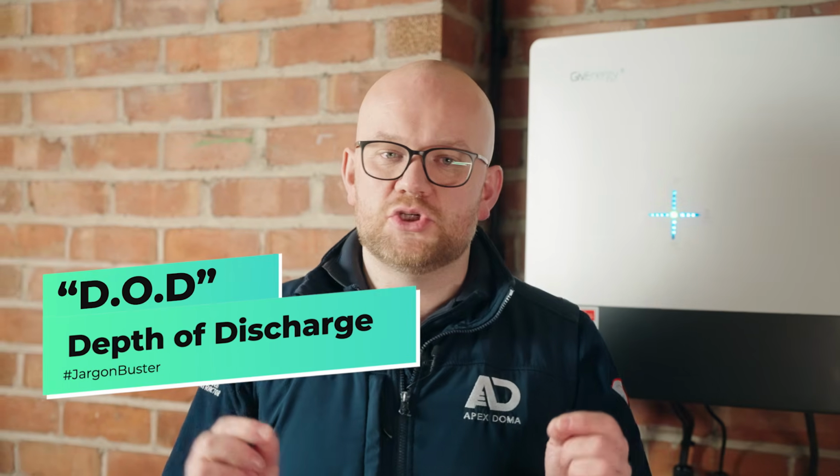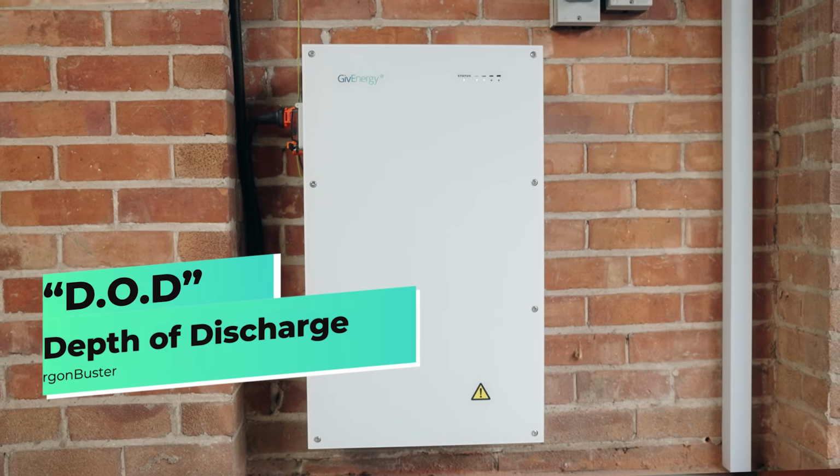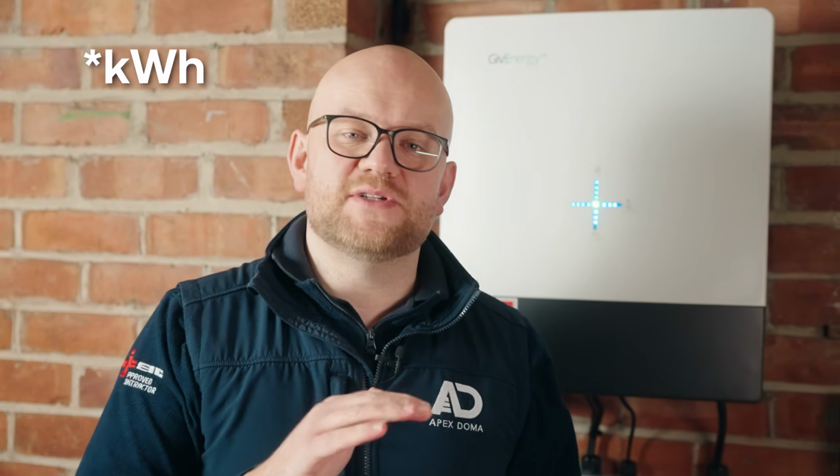Something else to give a bit of thought towards is a thing called depth of discharge, or DOD. With this battery behind me, it has a 100% DOD, depth of discharge. What that means is the full 9.5 kilowatts can be accessed and used. Now, for the purpose of this equation, imagine we now have a 10 kilowatt battery that's got an 80% DOD. What that actually means is it is 10 kilowatts worth of battery cells, but you can only use and utilize 8 kilowatts of the actual battery storage that goes behind it. So in your mind, think of this at this point in time, someone's selling you a 10 kilowatt battery, but you're actually only getting 8. So that's something else you need to consider when asking your installer about battery storage.